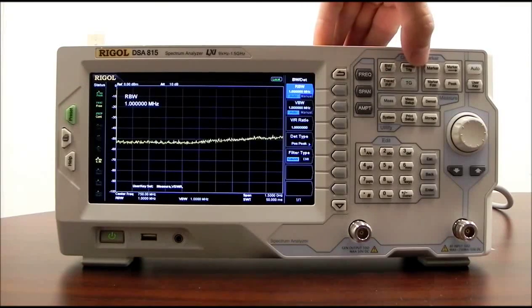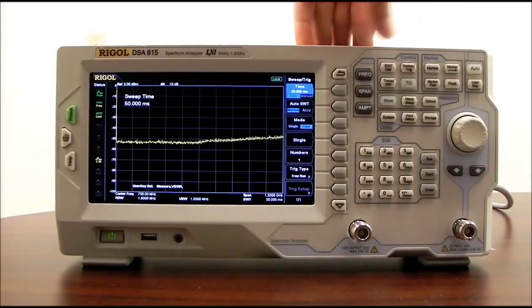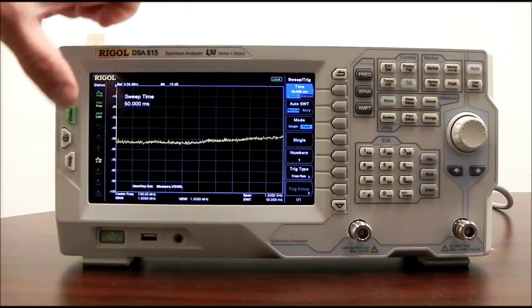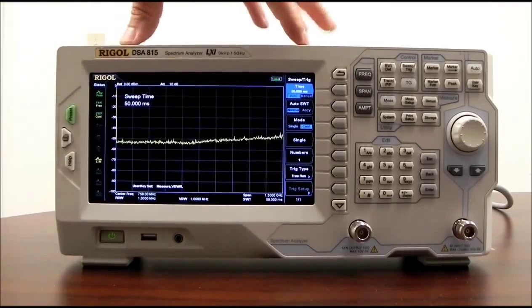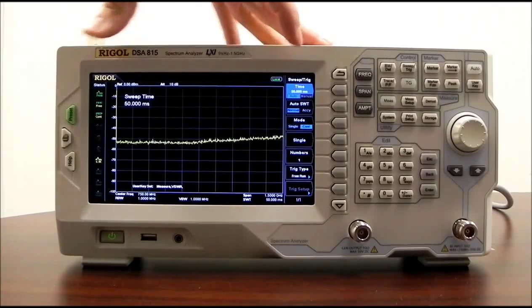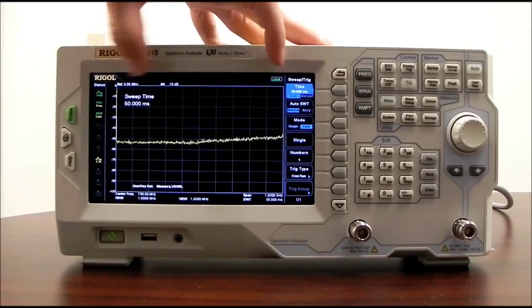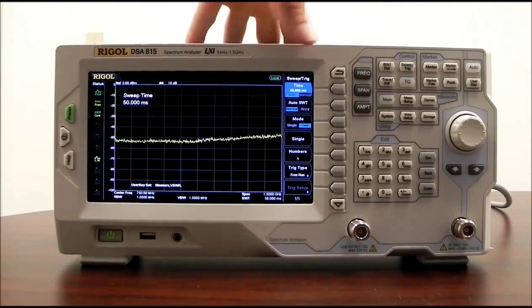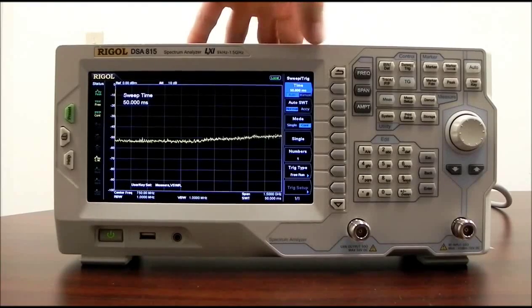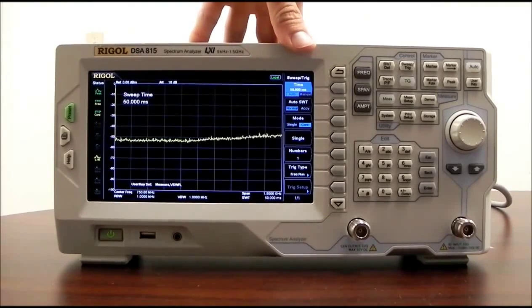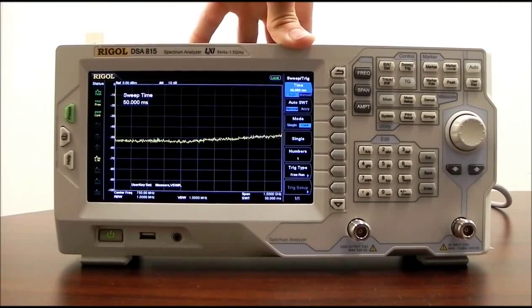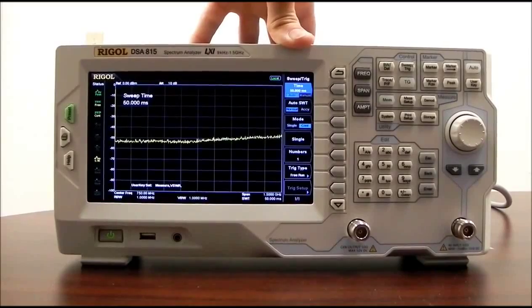And now let's take a look at the sweep and trigger. We can set the sweep time. Typically that sweep time is going to be on auto, and it's going to be based on the amplitude and the sweep configuration that we have set. The frequency range, the span and the resolution bandwidth are going to determine that sweep time if we're in auto mode, and that's going to be calibrated. If we go to a manual mode, that's going to be uncalibrated because we're actually forcing the box to do things that it's not necessarily optimized to do in a calibrated sense.